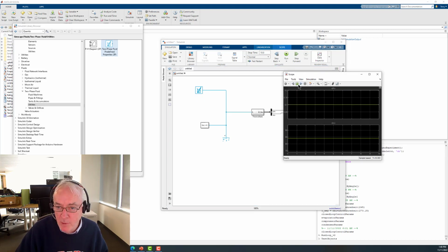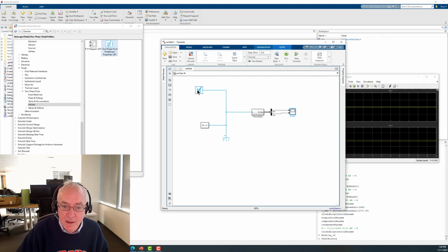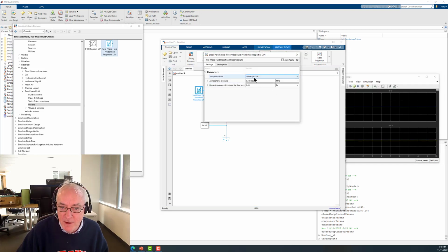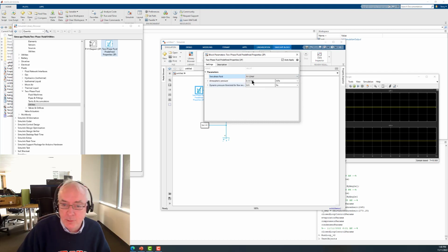Let's actually run from the scope itself. And you'll see that our default fluid clearly was water, because nothing changes here, and that's the default assignment right there. Not sure what R718 means, but I'm sure there are specifications and standards for water too. But we're going to use one that was used in our initial demo, and it's called R1234YF.